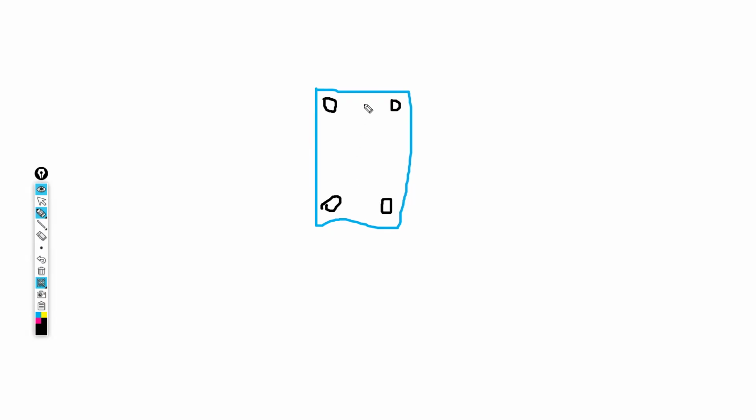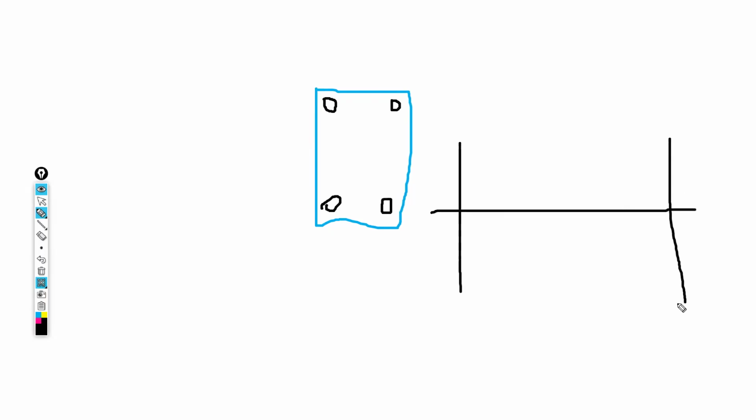If they are at the top of the beam, that means that at the support, where you have the beam crossing the column, that's where I put additional reinforcements. Because if this is your base frame, columns and beams, when this beam is deflecting, it's going to deflect in this format. So at the support, we have hogging moments. These are called hogging moments.